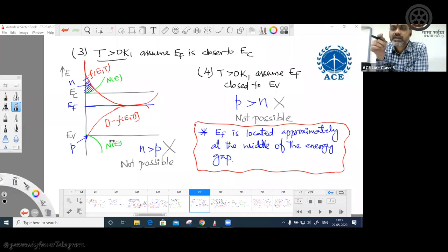But if you take the conduction band and valence band that we are talking about, there is a certainty. Are you understanding my point? Even there, if you see the numerical problem that we have solved, we calculated f of E comma T, no? Now you see the value, how much it is, 0.0 something. And still we calculated how many electrons are going to be present in the conduction band. We got in the order of 10 power 15. It's not a small number, no?